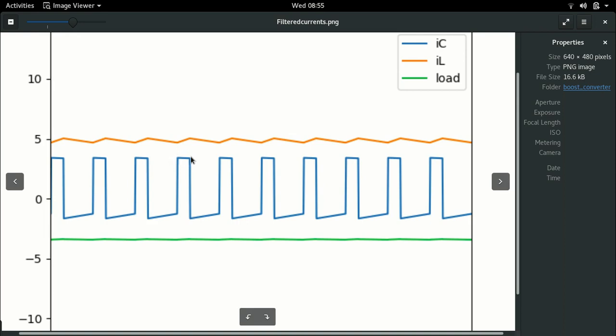And you see that it's almost constant. The reason is because the capacitor voltage is almost constant. We've chosen a large DC capacitor whose voltage is retained even though it supplies a current to the load. So that's why the current is almost constant, because the load is constant and the capacitor voltage is almost constant. There will be a slight change, but very slight. It is the other time, that is when the capacitor is charging.